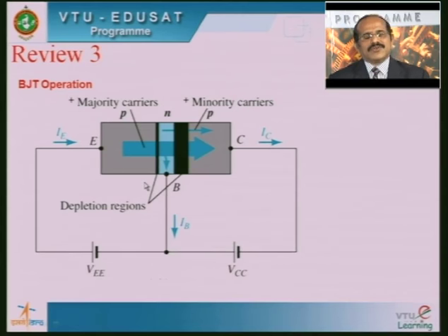As you noted in the semiconductor junction theory, whenever a junction, any device, is either forward bias or reverse bias, a depletion region exists across it. As you know, the emitter base junction is forward bias and the collector base junction is reverse bias. Usually the thickness of the depletion layer across the collector base junction is more compared to that across the emitter base junction.